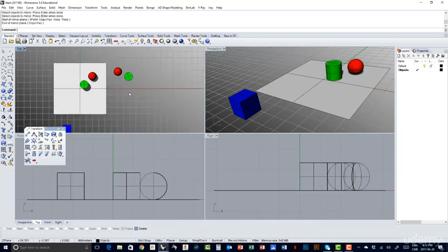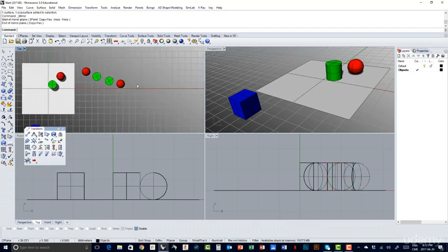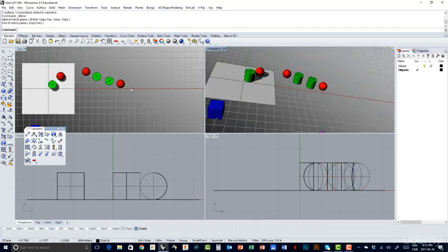So left click and I define the axis of my mirror. Okay, so again I can choose them all at once like this. I choose mirror, my cursor converted into a crosshair, so I put the first point of my axis, and then I can put the second point of my axis wherever I want, for example here, and there you've got your copy and your mirror. Okay, so try and play with these little functions.